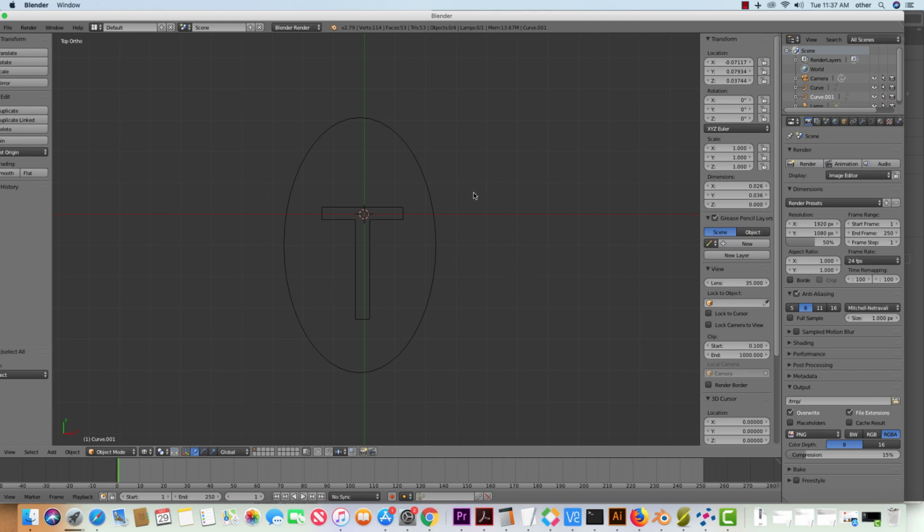Alright, to go back into 3D, you hold Alt, left mouse button. Just practice Alt, left mouse button for a second. Now Alt, middle mouse button allows you to pan, it's called. And Alt, right mouse button allows you to zoom in and out. So take a second to orient yourself with the navigation before we begin.